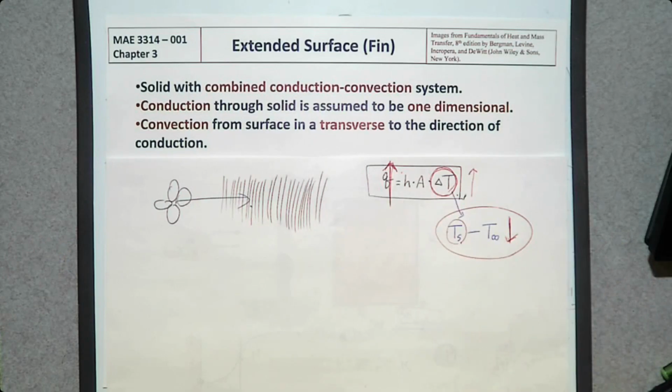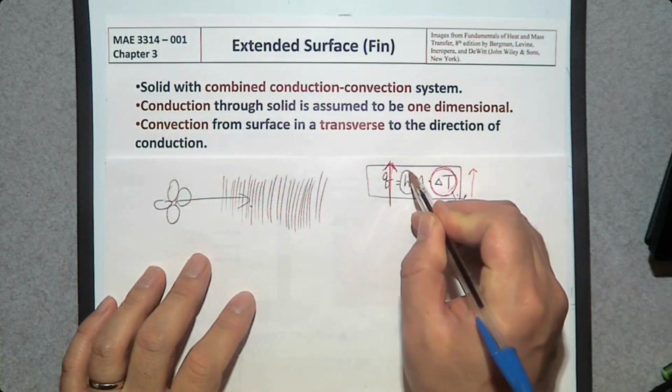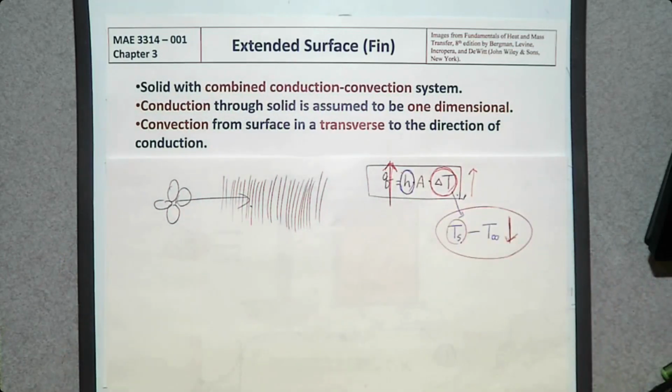So let's think about another way. Oh, maybe we can improve this h. How can you improve this h? So there are two different ways. First, you can increase the forced convection. You can increase the air velocity. So you can suggest in the owner's manual, if you want to increase the cooling of your engine system, drive faster.